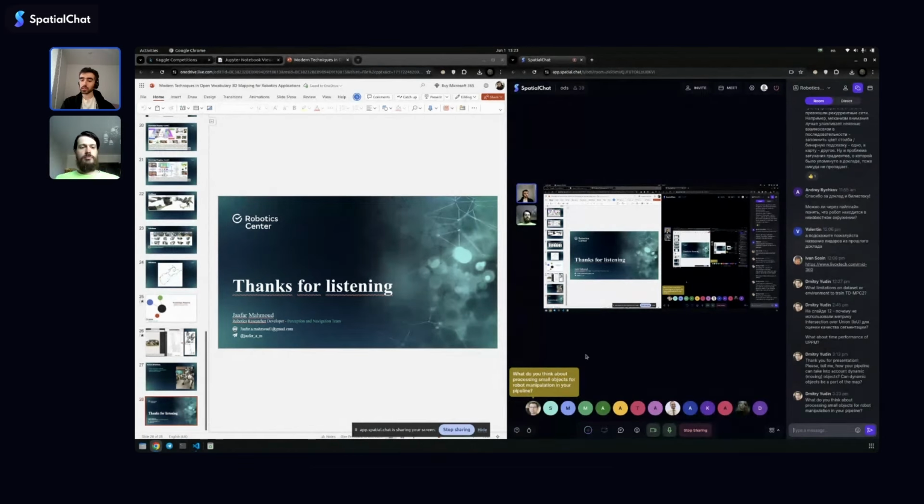And about the accuracy being worsened by the effect of dynamic objects, we can remove these objects at the level of visual odometry and at the level of LiDAR mapping, so that it won't be a problem. We don't consider the points on this object for pose estimation, but we consider them for building the agent in our map. But right now, no, we haven't.